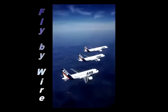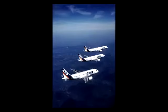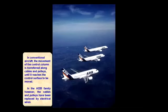We will begin this module by explaining the basic concept of the fly-by-wire system. In conventional aircraft, the movement of the control column is transferred along cables and pulleys until it reaches the control surface to be moved. In the A320 family, however, the cables and pulleys have been replaced by electrical wires. This has the advantage of saving weight on the aircraft. However, there are even greater advantages, as the video clip will demonstrate.